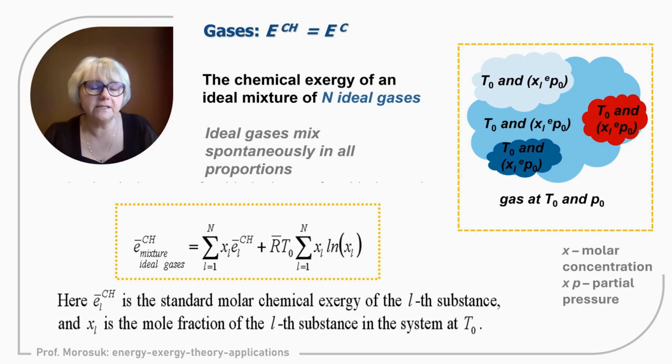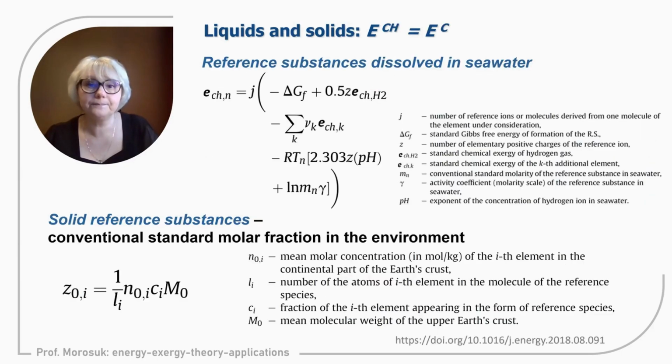several ideal gases. And we know that ideal gases can mix spontaneously in all proportions. Therefore, we can adjust the equation with many chemical substances with corresponding molar concentration. So this is very important: we always discuss molar concentration for each substance within these gases. And of course, it will be associated only with concentration exergy, because it will be the concentration of each substance.